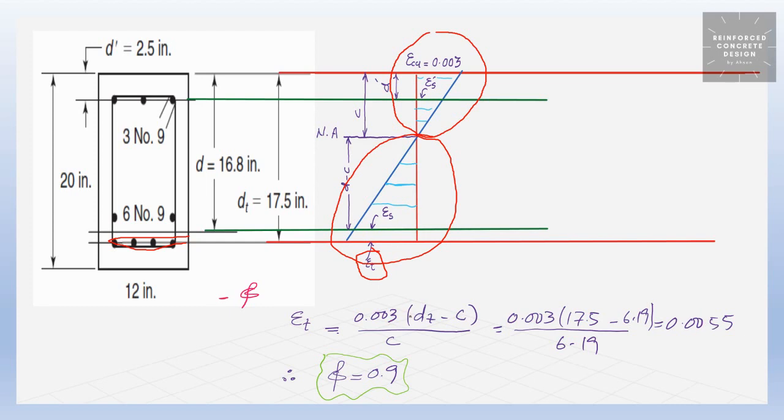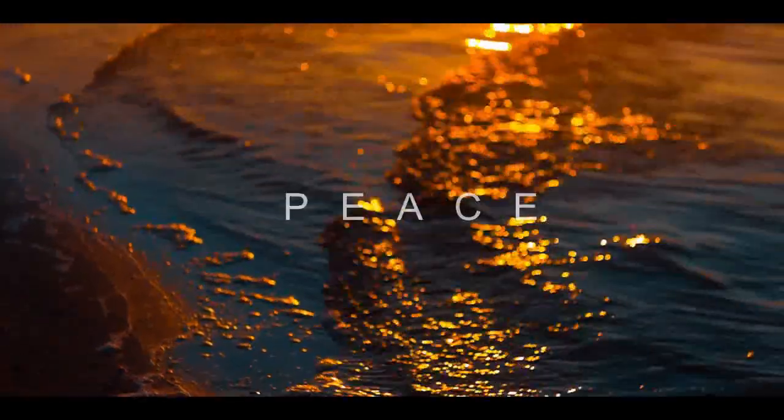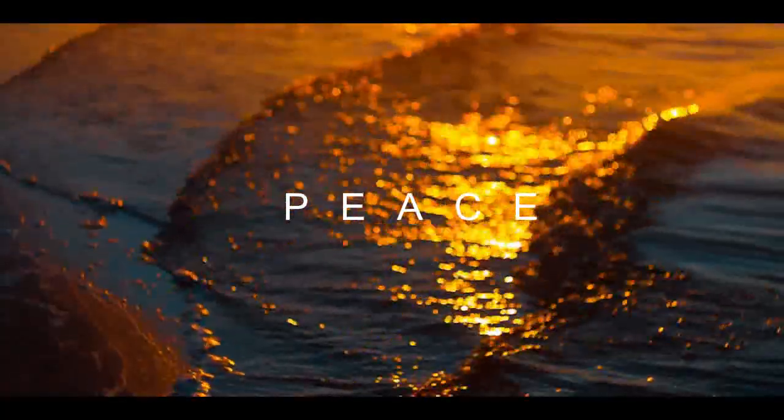Now this formula is equal to 0.003 multiplied by d sub t minus c over c. d sub t is nothing but the distance of the bottom layer of reinforcement from the top face, and c is the depth of the neutral axis, which is this one. Since I have already calculated this value using equilibrium, which is 6.19, epsilon sub t is equal to 0.0055, which is greater than 0.005, and hence the phi value is 0.9. I hope this video has cleared some of your concept.